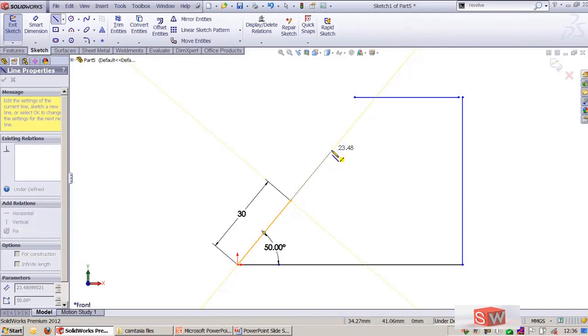And there is one more thing I want to highlight here. When you create a line segment, you can also create an arc continuing with that. Before that, let's complete this inferencing. Like you can see here, when I move near to any of the line segment, it will show you the end point, or I can drag from here to get this midpoint. Now you can see the midpoint from this line segment. Okay, now I will show an example. From here I will get a point, and from here also you can see a midpoint you can choose. So this is what we call an inferencing point.